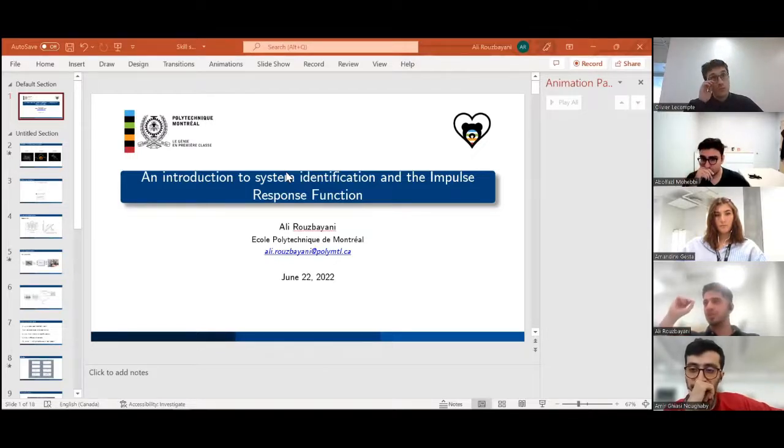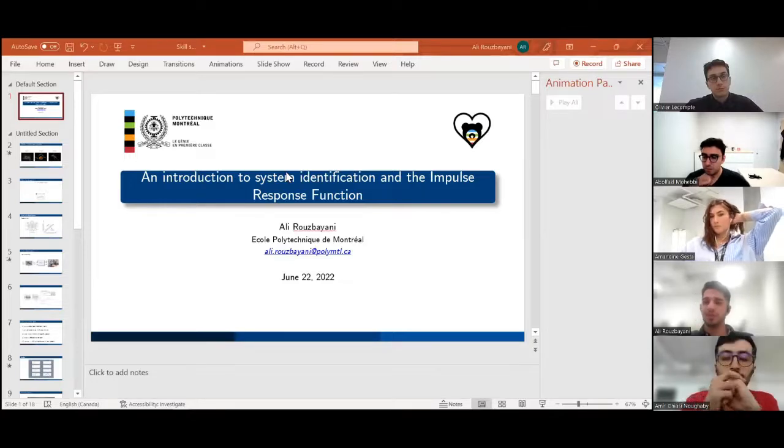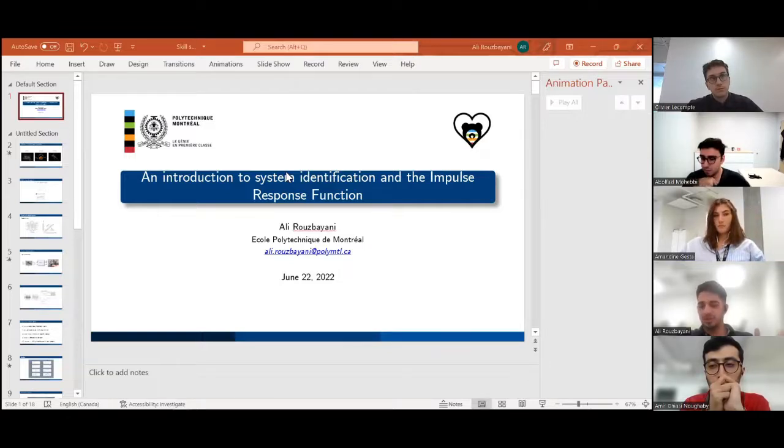one of the key features of system identification is that we give the system the input that we desire. We design an input based on our algorithms, and we feed it to our system and then observe the data. Whereas, I believe that for most learning, like supervised learning, we are always given some data, or we collect some data. We cannot stimulate the system with our desired type of input. This is one main difference that I've noticed.